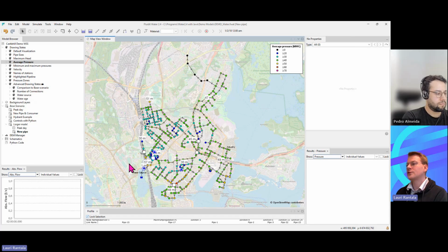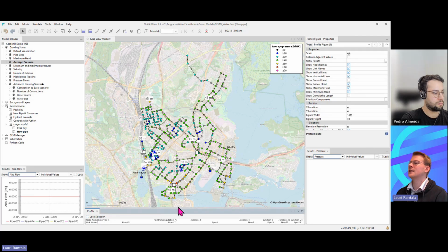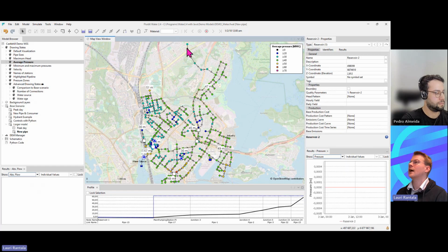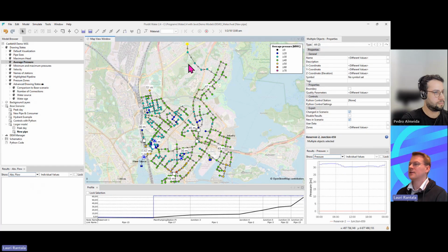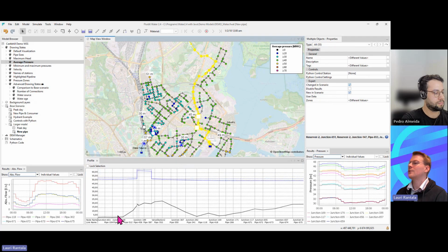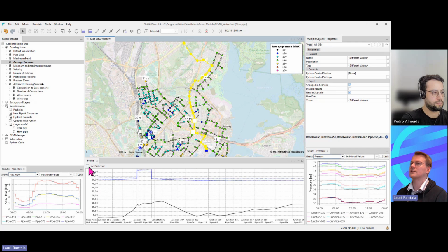And that's always important to remember, that you always have to simulate to get an understanding of the changes you made. So I will click F5, and now the new pipe here, I would be able to understand the pressures of that. And I could, for example, take the profile from my reservoir 2 and control button down, selecting this, and find the best route between these 2 points. It would be able to then find the route from the reservoir to the point that I just created.